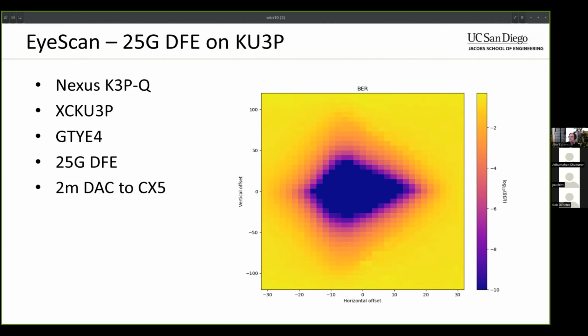And it works with the DAC. A 2 meter DAC works just fine. But at 100 gig, it doesn't work. You can go in with the, what is it called? The System Console thing in Quartus over JTAG and manually plug in all the settings, and then the link will come up through the DAC. Or you can plug in an AOC and then it'll work with the default settings. I even have a 30 meter AOC and it works fine because it has the retimers in the modules. So I don't know what's going on with that.